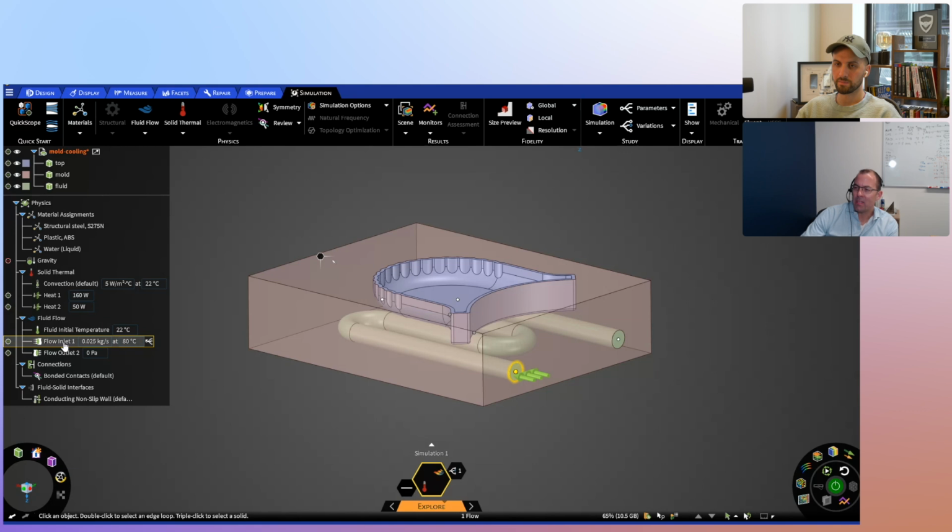So we're trying to maintain some sort of temperature. And again, there's a whole system and infrastructure in the back end with a heater and a pump and everything. And then generally speaking, we're going to have some outlet. I've got this set to 0 gauge pressure. In reality, it's not going to be 0 gauge pressure, because again, you've got a whole cooling circuit that's going to be out in the floor, and maybe even being shared with other molds depending on how it's done. So I've just simplified it a little bit.